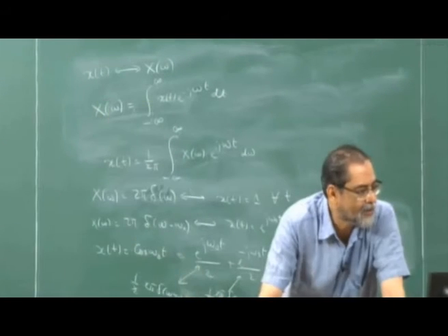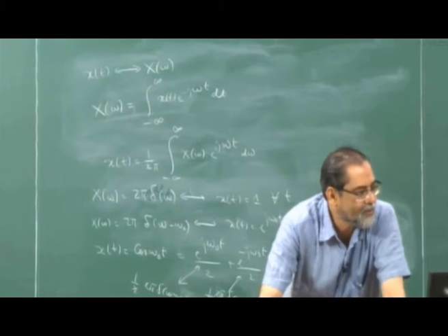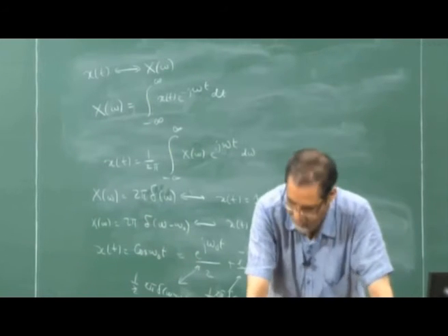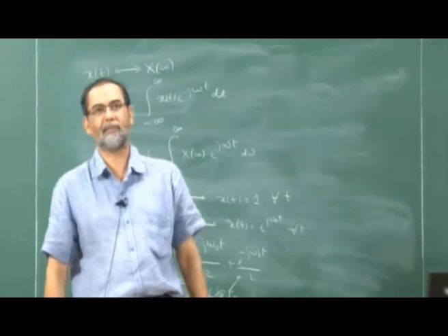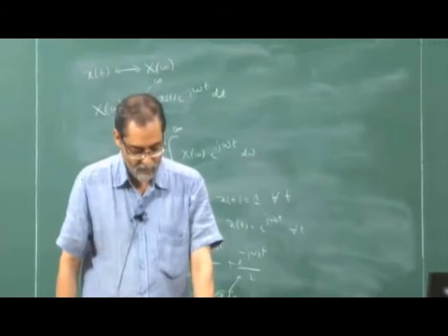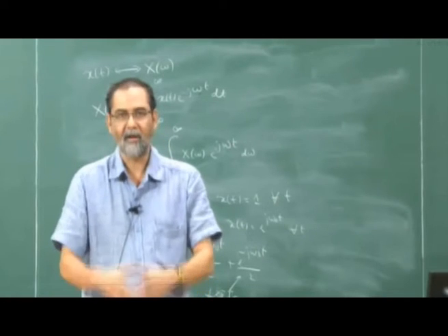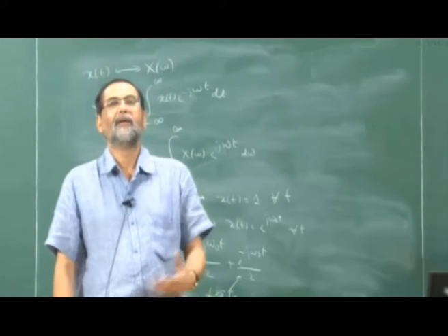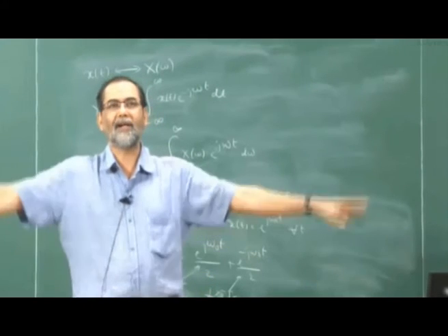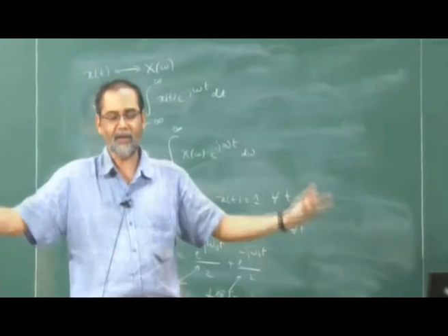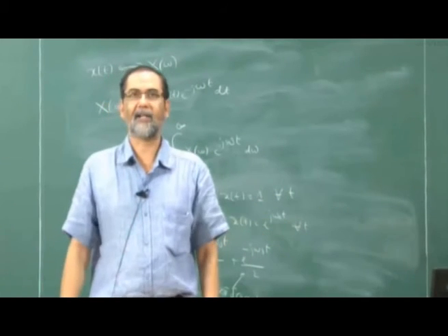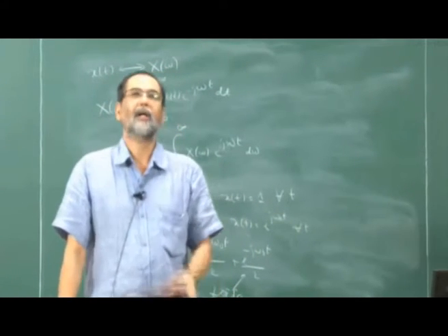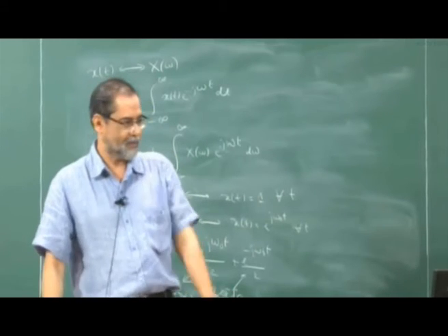There's a question from PSG Tech that says, periodic signals are power signals. Yes, the answer is yes. Periodic signals are power signals, right? Square integrable, right? So, when you integrate them over a period, you can integrate them, but if you integrate over the entire length, you cannot, because periodic signals don't go towards 0 as t increases in both the directions. So, periodic signals are power signals, correct.